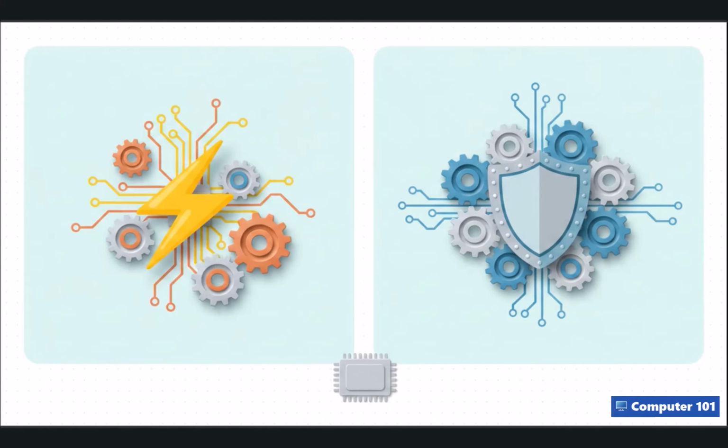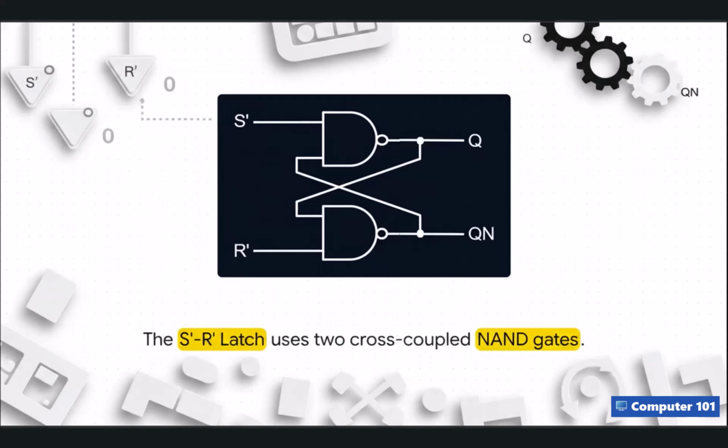So, how exactly did engineers solve this whole amnesia problem? Well, enter our hero, the sequential circuit known as the latch. Before we peek at its schematic, just notice where latches fit into the broader family tree of memory. Latches are the faster, simpler, level-triggered siblings to edge-triggered flip-flops. They're incredibly efficient, for sure, but as you'll see, their simple design can actually cause some serious, system-crashing timing problems later on.